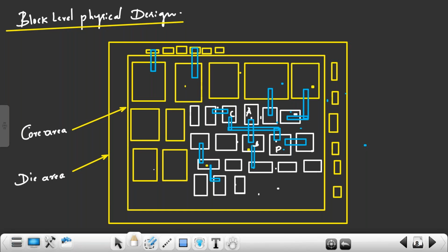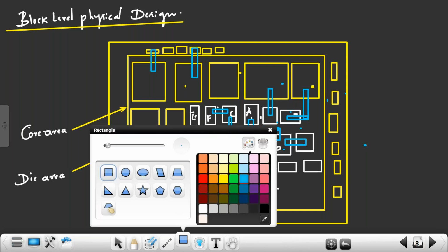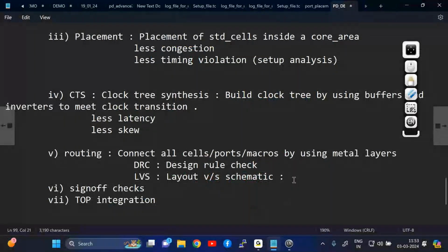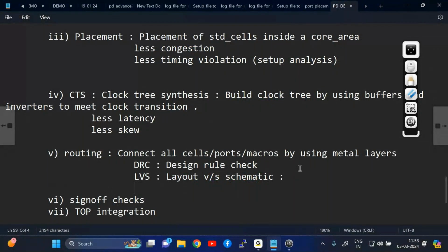Layout. So, for example, this E and F cell should connect to each other, but for some reason they are not at all connected. They are left unconnected. In the netlist there is a connection, but in the layout there is no connection. Then this is called as opens. So you will study shorts and opens after LVS: why there are shorts, why there are opens, what the reasons are, how to fix it. Shorts and opens are analyzed.